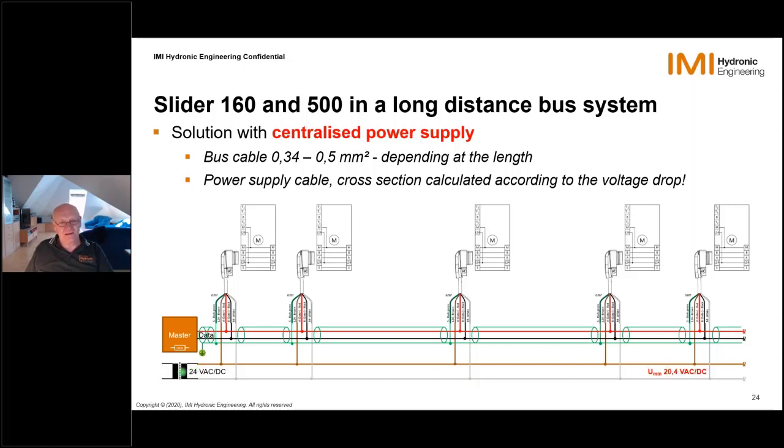As I explained before, this reduces our voltage down to the absolute minimum. Then either you make this cable thicker, or you feed in locally with an extra power supply. But take care, we are not allowed to exceed this 1 meter.